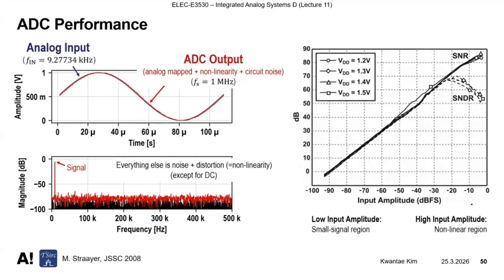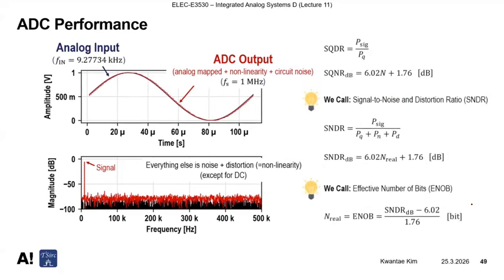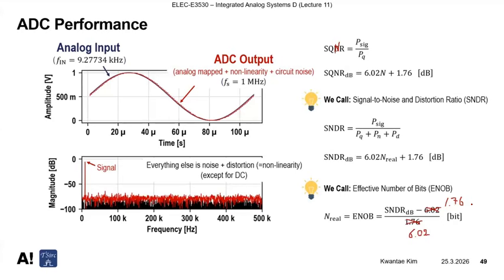And this is a very typical measurement result you can find in research papers. So you basically sweep for measurement of SNDR and SNR. Here, SNR is calculated without distortion. So for calculating SNDR, there are FFT bins, right? Those are all digital output values, and for each frequency bin you have values. So you take signal, you take DC, and everything else is what we don't want. We just simply add them up in power domain.